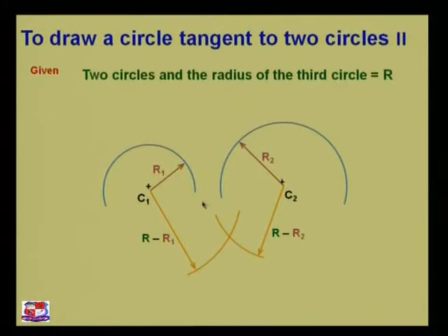It is not necessary that r1 is equal to r2. Sometimes the radii r1 and r2 would be totally different. So you need to subtract the exact figure to draw this arc. No matter what the difference is, you will get the center point needed to draw the tangent circle.